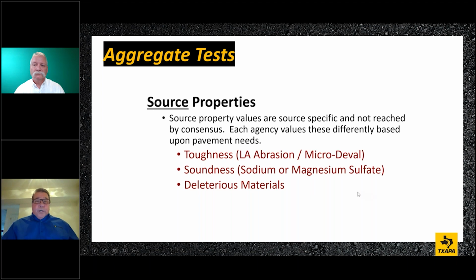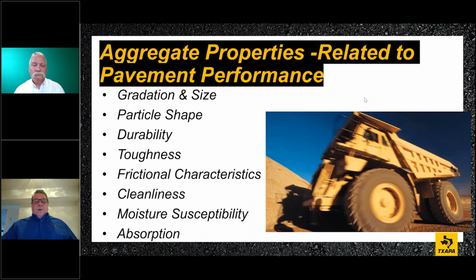You know, we could have wood, and we could have blasting wire. We can have plastics that come from the blast. I've seen that quite a bit. Blasting wire and plastics come from a blast. That's deleterious material. That's going to have an effect on our aggregates. So we need to make sure that we have good, clean, sound aggregates for them to act properly.